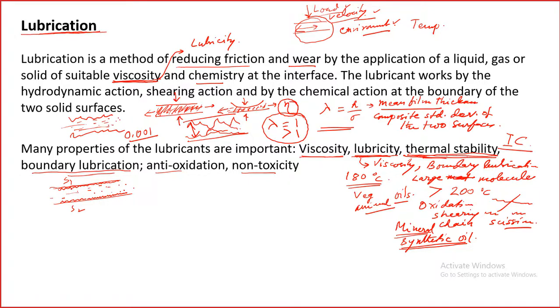But people explain that under high pressure and some temperature, this reaction will take place. So the molecules in the liquid or lubricant will react with the solid surface here and form a layer just like a coating, a very low shear or soft, low shearing layer. So this is known as boundary film, and this method is called boundary lubrication.